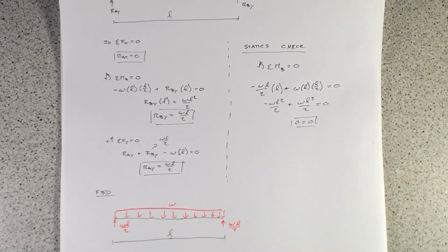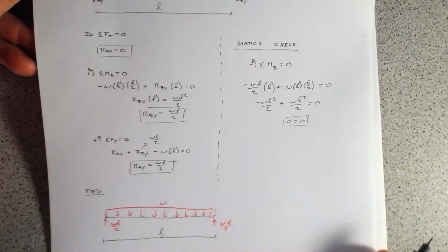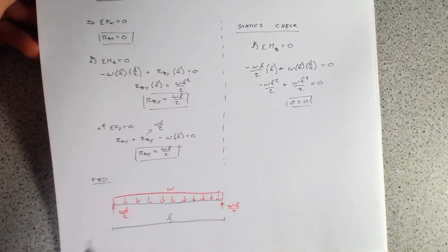And so what we're going to do is start basically by taking free body diagrams along this beam. We'd think of this as the brute force method. It will always work, but it is maybe just a little bit slow. So that's what we're going to do next, to find the shear and bending moment.